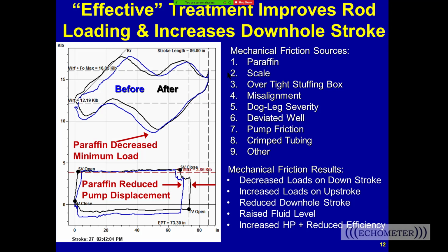I'd go look at wells that had rod guides in them, and I wouldn't see any increase in the load. So I didn't think that rod guides created that much additional friction. In fact, they don't create much additional weight. If they're not too abrasive, they don't even show up. That's what my experience has been. Now, if there's a lot of abrasion, they can show additional friction.